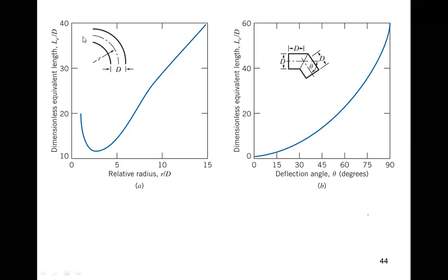So this is the bend here. You are changing a direction of the fluid very smoothly here. So if your diameter is larger, this R is more and more, your losses would become less and less. Best example was your car only. If you take along the radius, you need not put a brake and anything. So you can move at the same velocity.